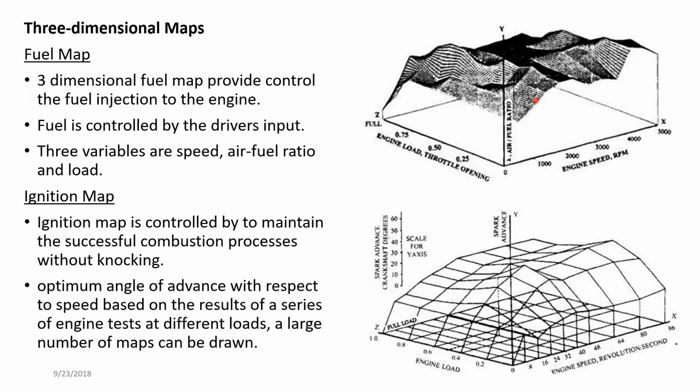The ignition spark will be retarded until it is able to completely stop the knocking occurrence, right? That's what is basically happening here. The management of this complete system, the fuel and ignition, is done by the engine itself.